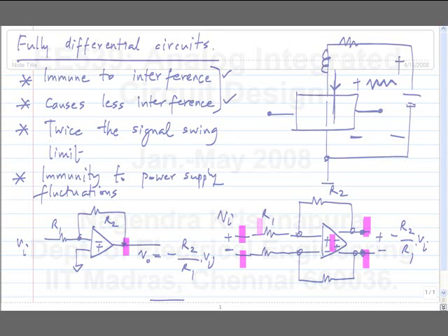Let's say it's your audio or whatever. It will be the differential input Vi. So we will make the feedback circuit for our signal and the common mode is assumed to be set within the op amp, but it needs to be set. Okay. And for that we need another feedback loop. Okay. We have two variables. To set two variables we need two feedback loops and the two variables we choose to set are the differential and common mode outputs. Okay. So any fully differential circuit that we make must have some way of setting the common mode output. Now it may not always need a feedback circuit, but frequently in high gain cases and certainly in case of op amps, you do need common mode feedback circuits.